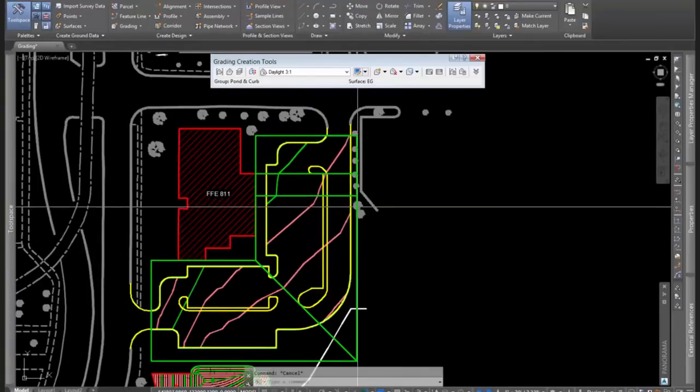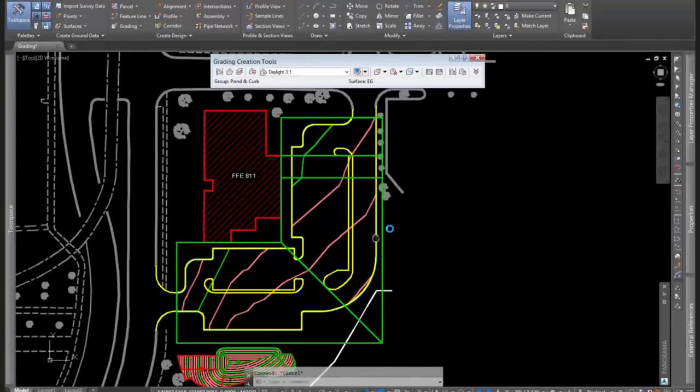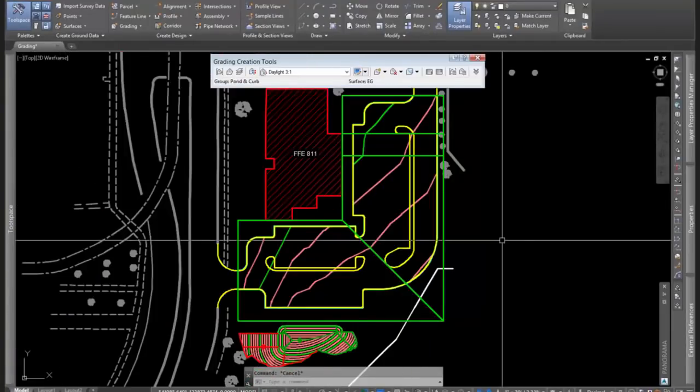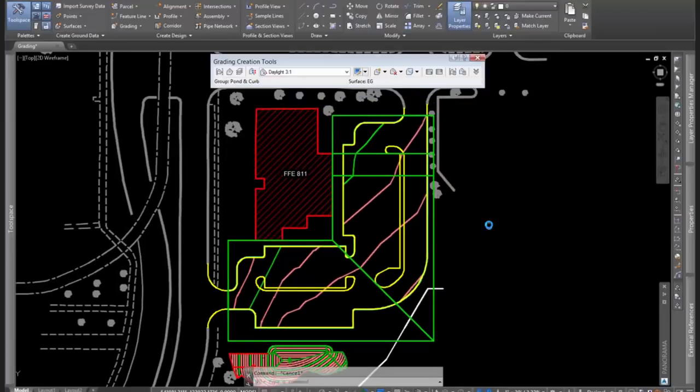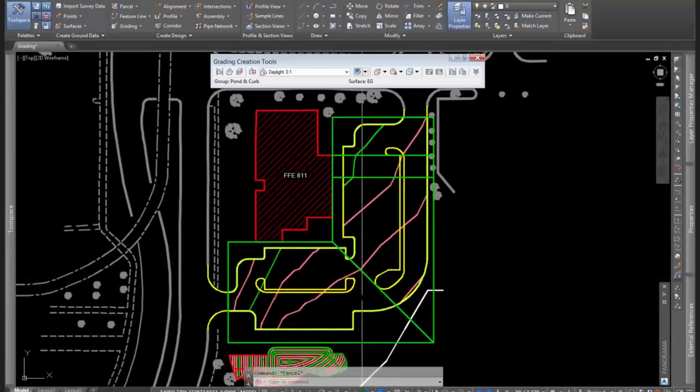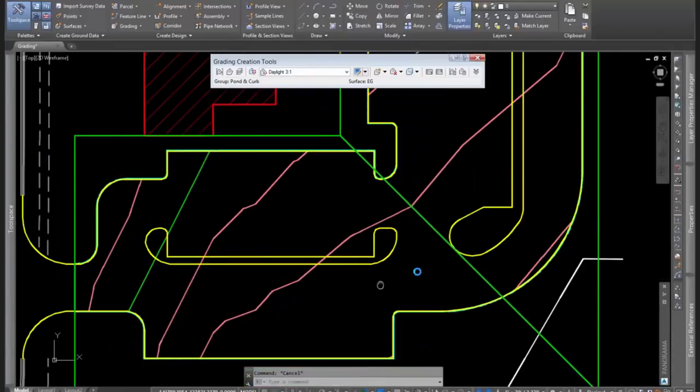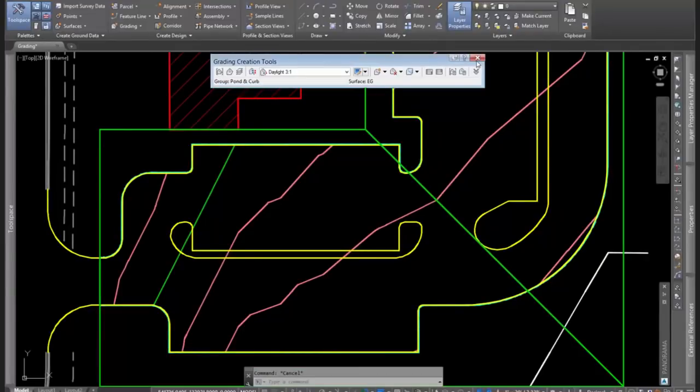Okay, I'm not going to spend a ton of time on the design, but this is how we want to put together our drainage surface. We want to look at overall drainage patterns. We need to think about, of course, where are our curb islands, where are ridges and swales and catch basins, and we want to design accordingly. But we want to have a fairly basic surface like this. And the reason is because from here, I can create my curbs fairly easily.